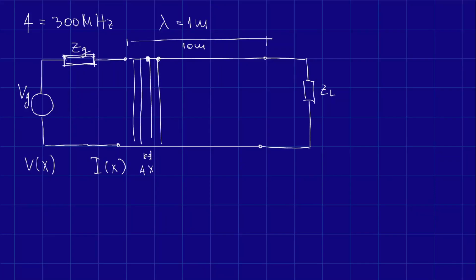And if we see things like this, we will have that the impedance is, as always, R plus j omega L, but here it will have a different unit of measure, which will be ohms divided by meter. And why is that? Because the impedance isn't the same everywhere in the transmission line. It depends on the position. That's what our divided by meter means here.